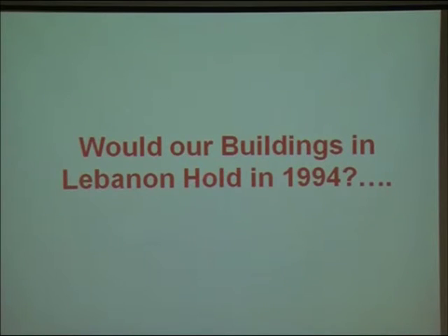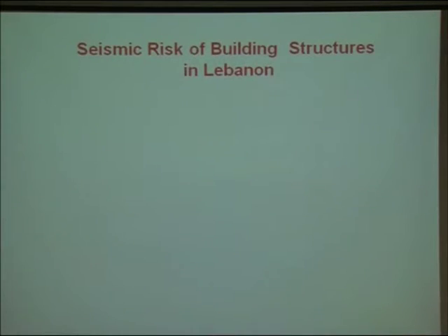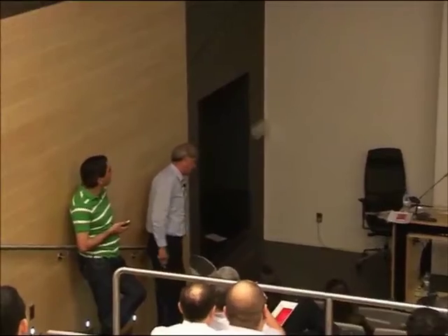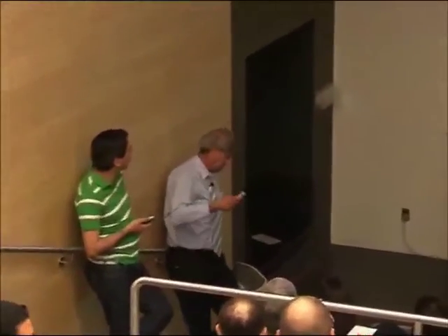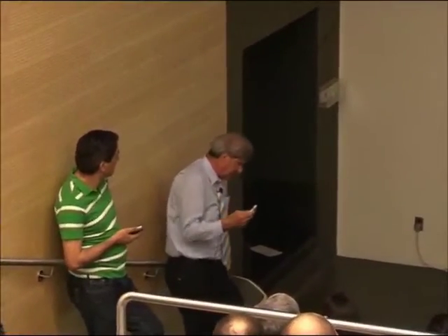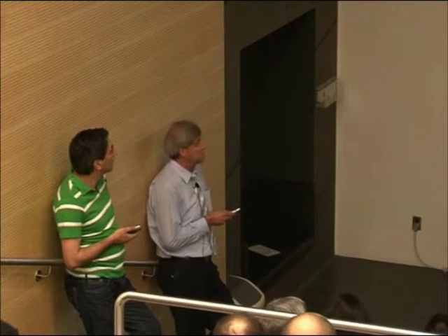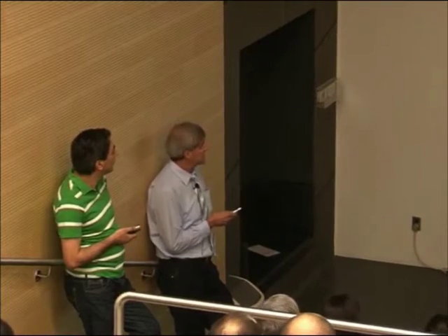So at that time, we asked ourselves, would our buildings in Lebanon hold in 1994? We did a survey of our buildings, especially why they are vulnerable in Lebanon. There are minimum or no shear walls. Shear walls are the most important structural elements that can resist earthquakes. Nowadays, we are advising the engineering community to try to depend heavily on shear walls, based on our experience in this area.